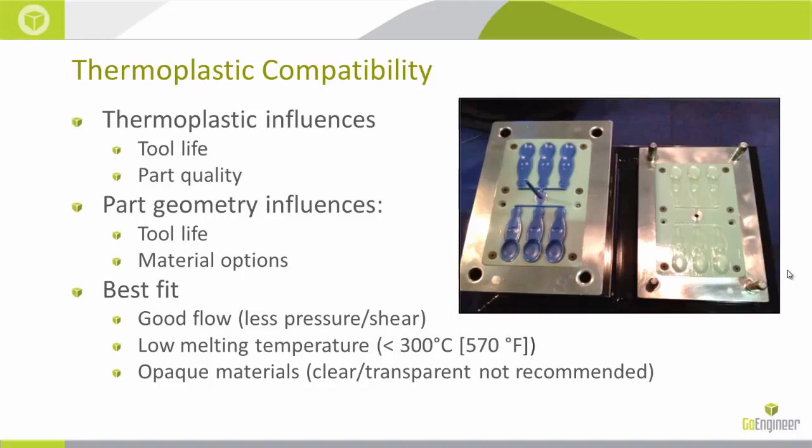Different plastics are going to be more compatible or less strenuous on our printed tooling. All right. Also the part geometry. If you have very high draw or very thin parts, that's going to be harder on the tooling than if you have thick walled parts with a low draw.